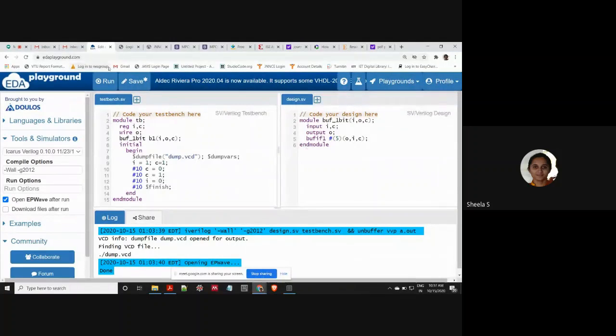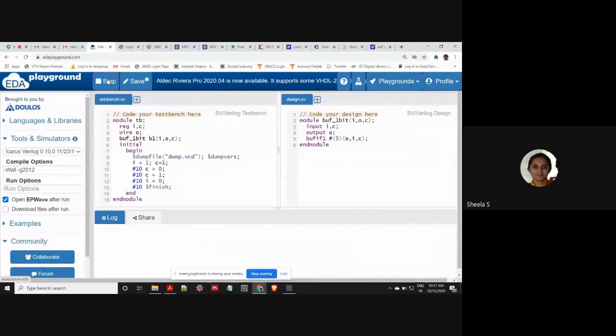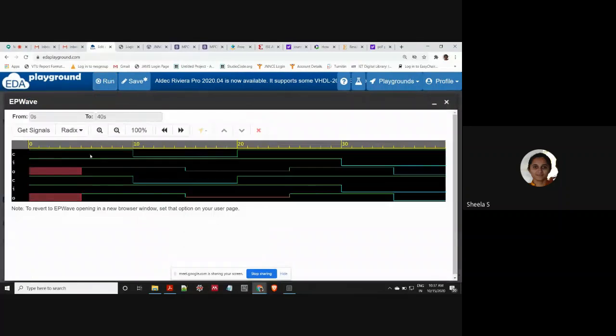So now when we execute this, for all the values it has to take 5 time units of delay. See here, as the input is assigned at 0th second, after 5 time units we are getting the actual output. Means it has been shifted by 5 seconds. Output waveform has been shifted by 5 seconds.